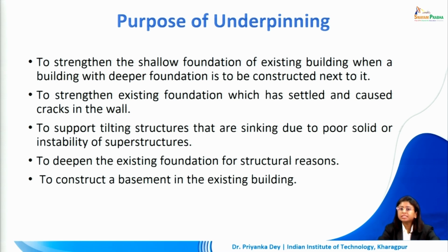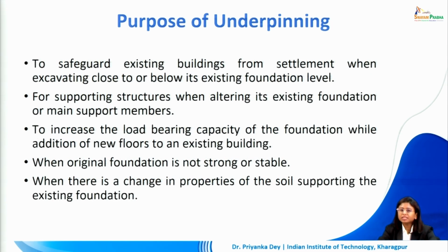If we are supporting any tilting structures which are sinking into the ground due to the poor stability of the soil, in that case we can go for underpinning as well. To deepen the existing foundation also, if there is any structural reason because of which we have to strengthen our existing foundation, underpinning finds usage. And also if we are trying to create a basement in an existing building, we will have to take the help of underpinning. To safeguard existing buildings from settlement, when excavation is going to happen very close to them,